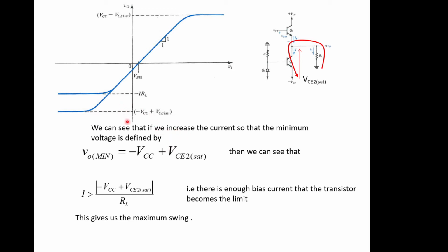What we want to do, as I said, is balance this. We define the current through the bias current, which we're free to set to what we like, and it needs to be this value minus VCC, offset by the saturation voltage of this transistor, which is usually about 0.2 volts, and then divide that by RL. So it's an effective application of Ohm's law.